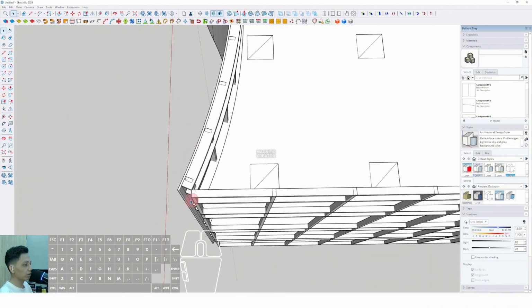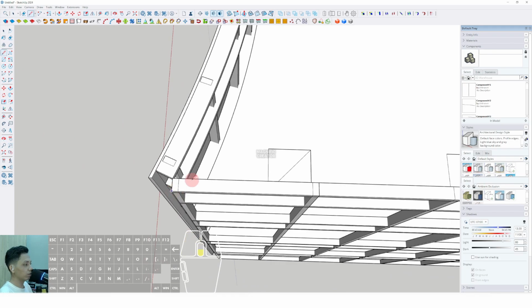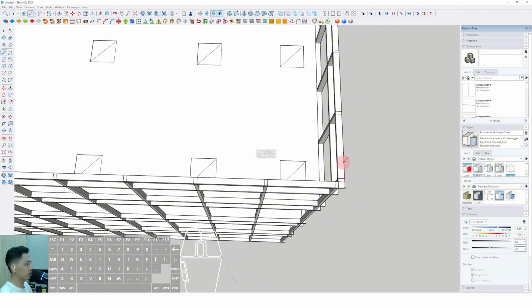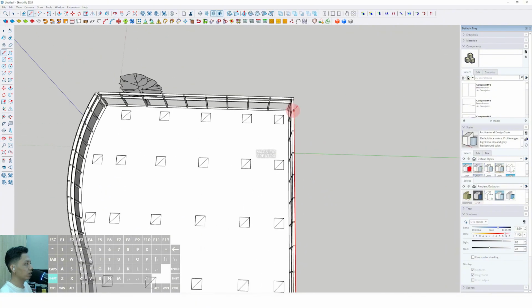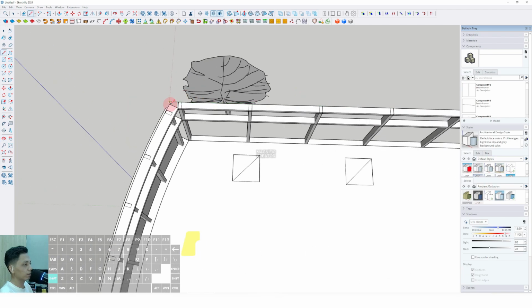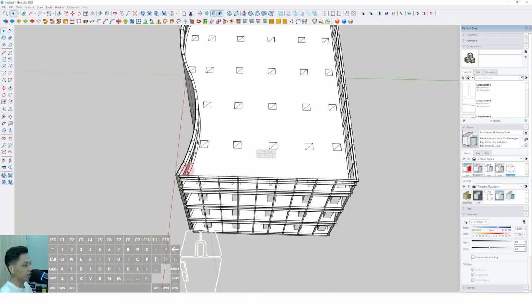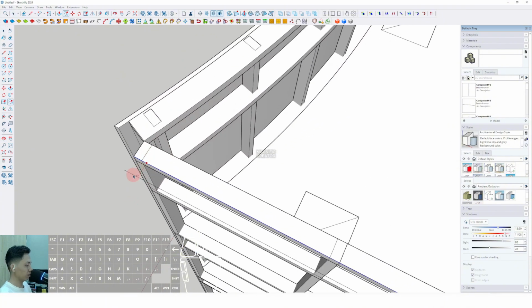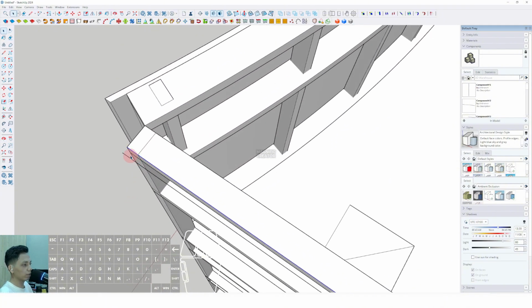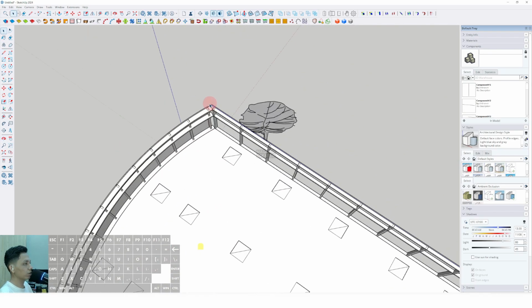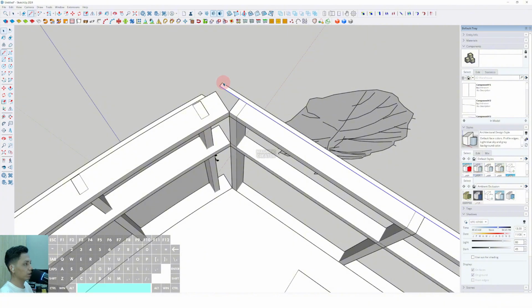Okay, then we can draw another glazing system using line and following every single corner over there. Okay, and we can triple click and offset it outside around 50 millimeter and enter, and we can close the polyline over there, and also close the polyline over there.